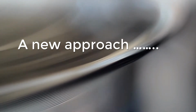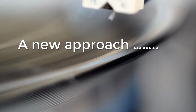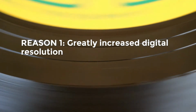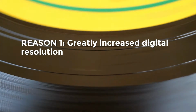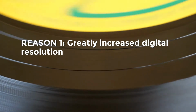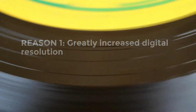Phaedrus and Spatial Audio believe that after 60 years, hardware phono preamplifiers have just about reached the end of the developmental road, and that equalisation is nowadays better performed in software for the following reasons. The human hearing system has a dynamic range of about 120 dB, and the very best analogue circuits can just about match that range. But by doing the equalisation and processing in software, we can use double precision floating point math, and that has a precision of 53 bits or 320 dB.